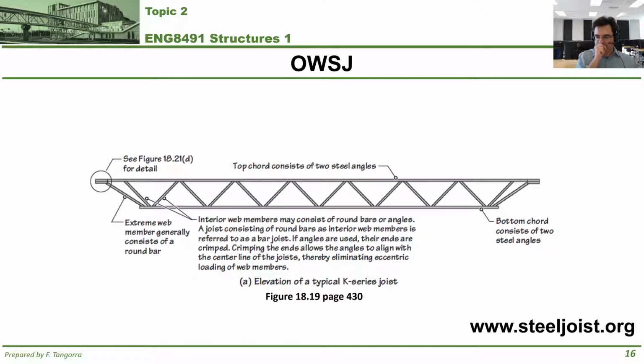They're the vertical portion of a beam. Well, these are called open web steel joists because the majority of their web is missing. Compared to, say, a solid I-beam or a solid steel beam, most of this structure's web is empty air. It's nothing.